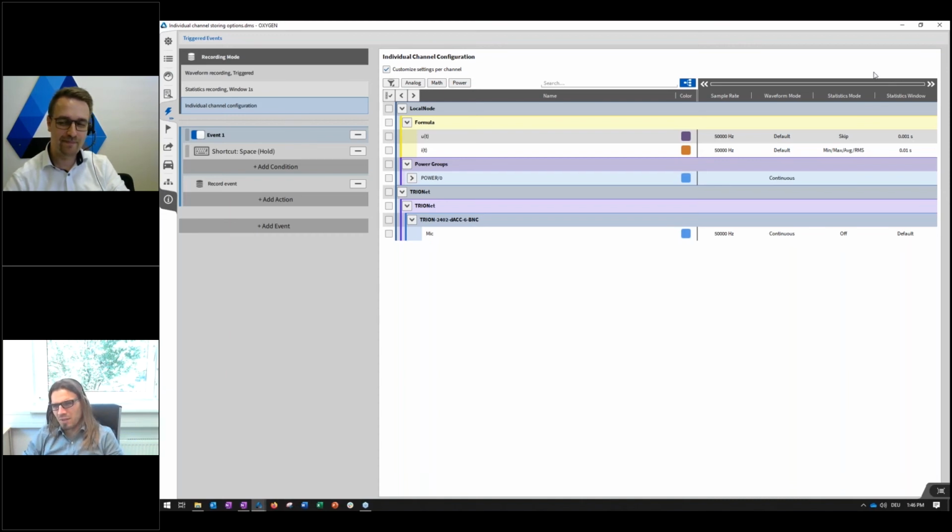Yeah, currently for the next release, which will be end of September, we are working on the so-called CPB spectrum. So a constant percentage bandwidth visualization of your data in the frequency domain. Additionally, to enhance the functionality of the sound level option a little bit more, we will also add a wave export and an audio replay functionality during the data acquisition and during the replay, so that you are able to replay some data channels by your sound card and to listen to them.